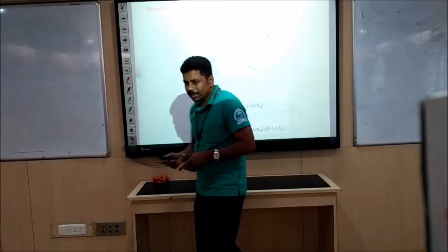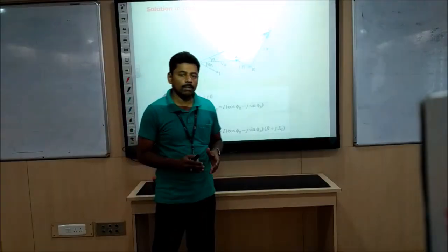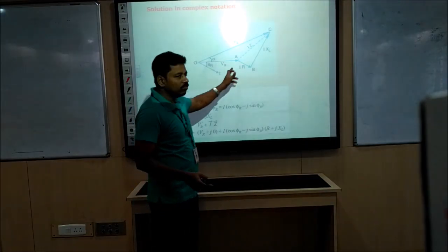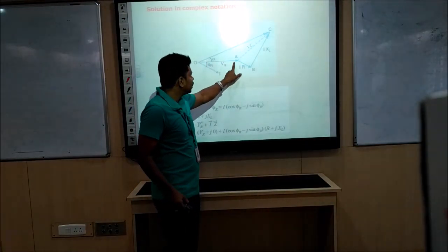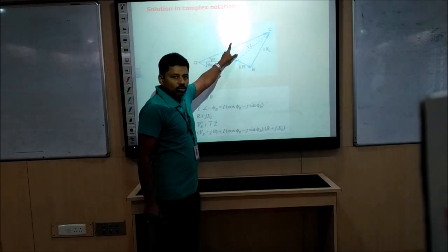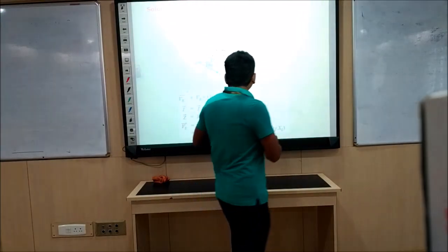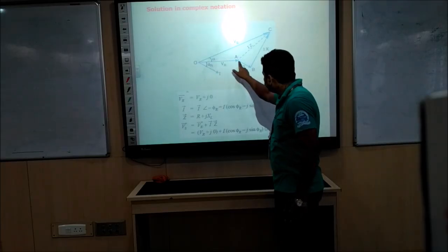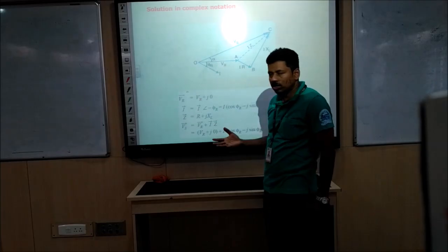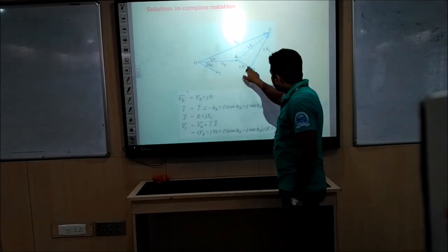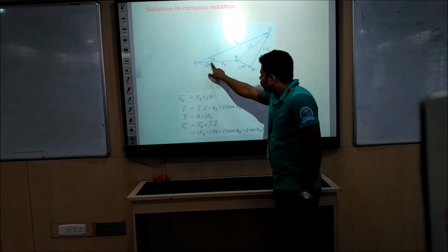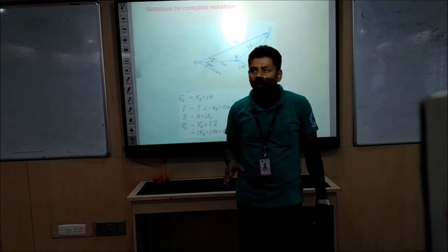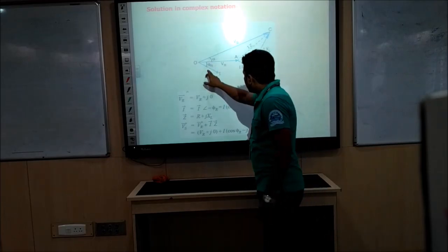In order to represent all these parameters, like sending end and receiving end parameters, we normally draw the phasor diagram. By taking VR as reference, to reach the sending end voltage Vs, there are two drops. One is IR, the other one is IXL drop, where IR is the resistive drop. Is is equal to IR is equal to I, we assume. This current is always lagged by an angle of phi r because most of the time the load connected to the transmission line is inductive in nature.